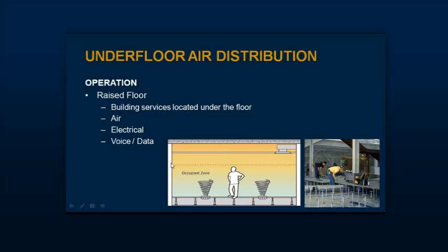Now there are returns incorporated that are these linear slots underneath these openings on the mezzanines. And the engineer at the end of this project was sort of flabbergasted. He estimated that we used one third to one quarter of the air volume in this space that would have been required to do this with overhead mixing. And of course, we had none of the aesthetic challenges that would often be found if you're trying to do mixing in a glass ceiling. It's just an amazing synergy how we were able to incorporate all of these elements inside this space.